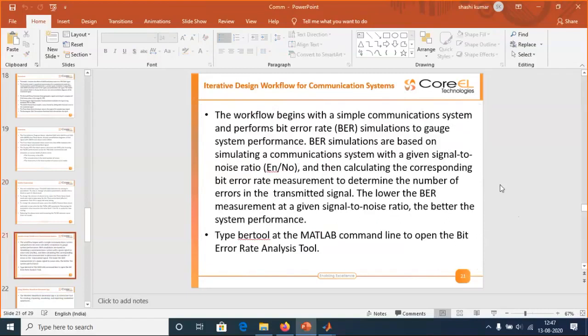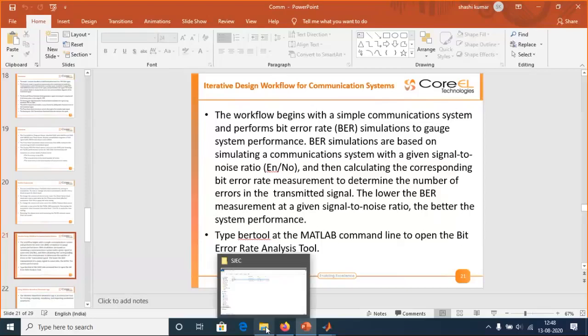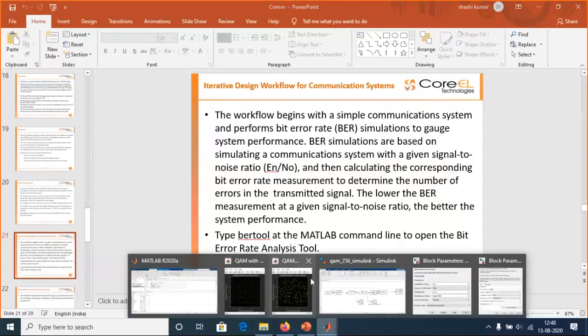So what this Monte Carlo simulation does is it actually has the complete set of parameters required for a complete end-to-end simulation. Starting from a transmitter end, what is the PN sequence it is using to scramble the data, what modulation technique it is, what is the actual signal to noise ratio after the AWGN channel, and how is it affecting the data, right?